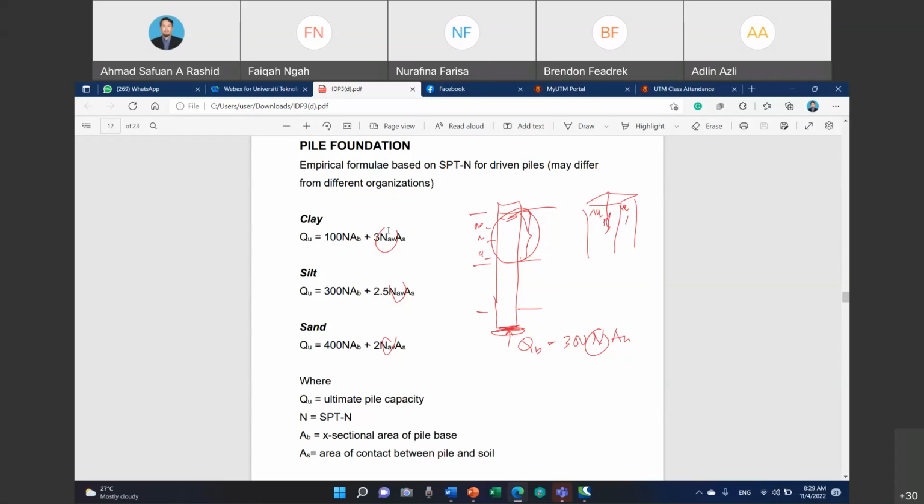Tambahan untuk dapatkan undisturbed sample, satu kita kena dapatkan when the SPT is less than 12 or 15. Okay. So kalau SPT more than 15, kita gunakan kaedah lain iaitu Mazier punya sampling, which is the SPT range from 10 to 20.